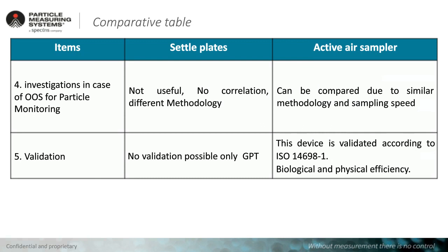Alternatively, active air samplers have been validated and can be validated according to ISO 14698 with the physical and biological efficiency. So you know that microbial air samplers, active air samplers, are working in the right way. This is what you are not sure of when you're using settle plates, and data out of these settle plates are very questionable. Therefore, I would now like to ask you some more questions, and I would like to hand over for this new interaction to Felisa, to get some new questions.